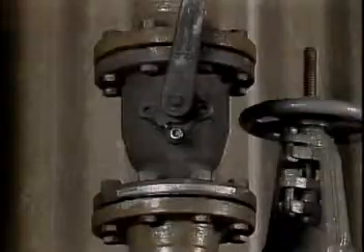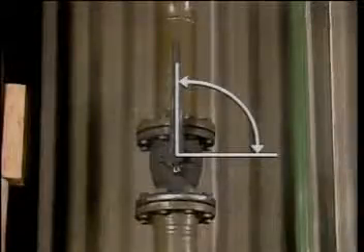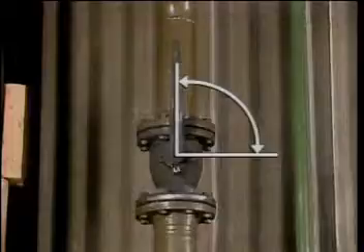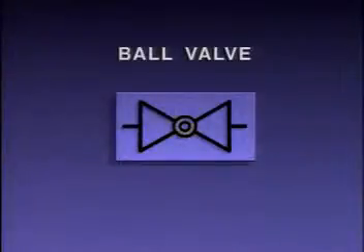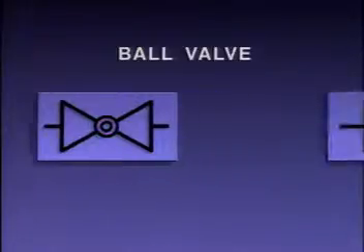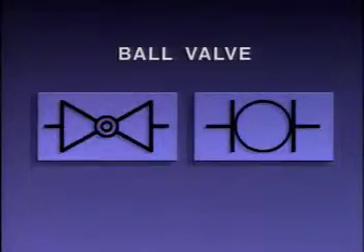Ball valves are similar to butterfly valves because they take only a quarter turn of the valve disc to go from fully open to fully closed. A ball valve has a ball-shaped disc with a hole through it. Ball valves are also sometimes represented using this symbol.